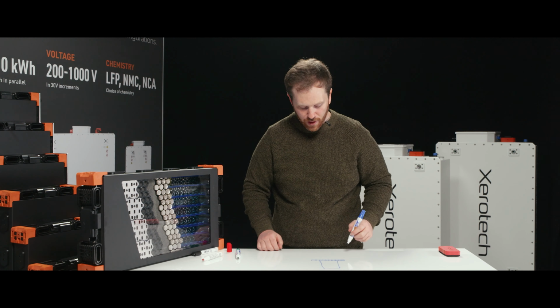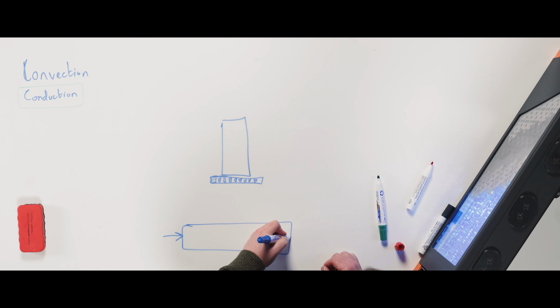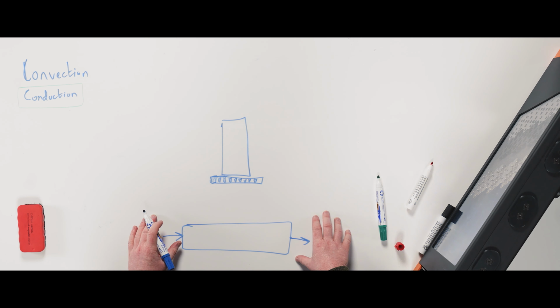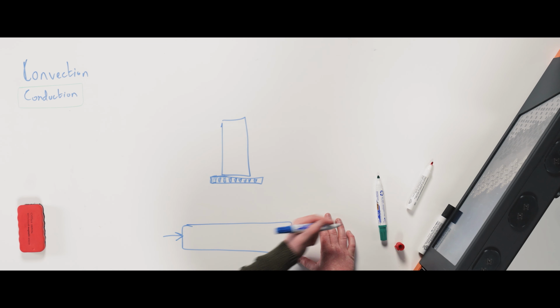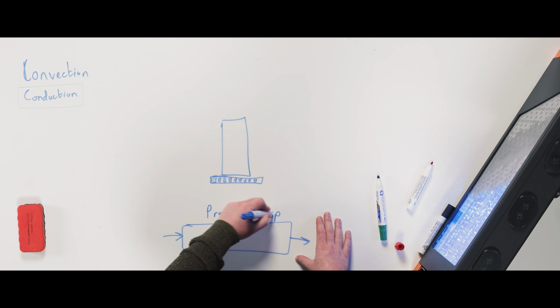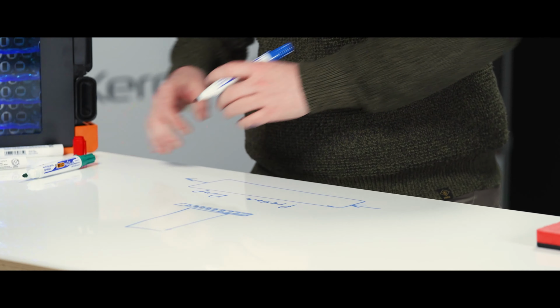And that means that as we flow through from one end of a pipe to another, I need it to be higher pressure on this side than here, because the water has to flow across it. And that means that you get something called pressure drop. You lose pressure, you lose energy. It takes power to pump water through something.